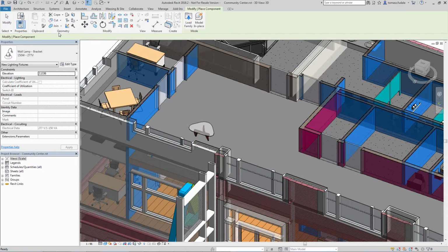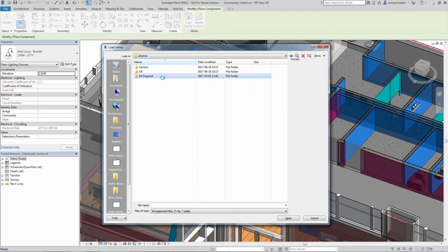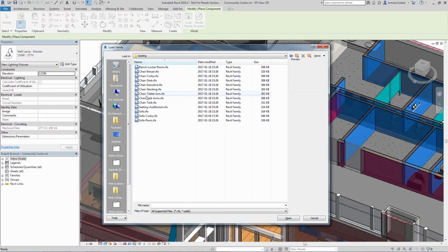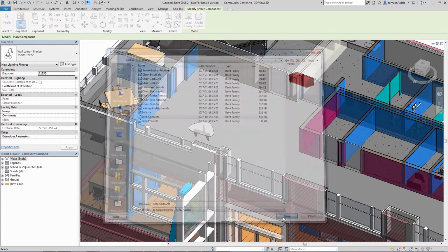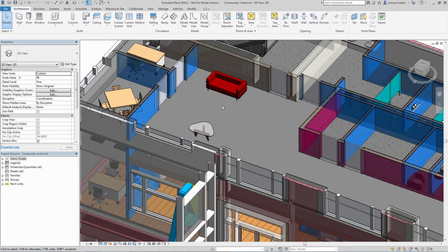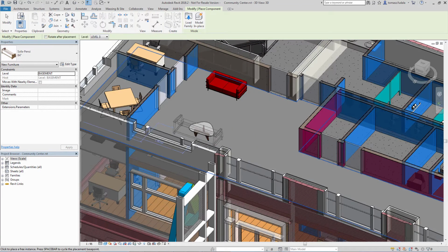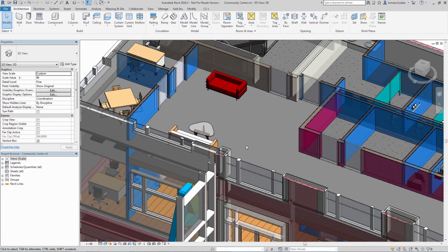In Revit 2018.2, once you load a family into the Revit session, the next time you load a family during that session, it remembers the location of the family you loaded last. You don't have to start from the default location and re-navigate to where the families are located. This improves your efficiency when working with Revit families, and you no longer need to rebrowse to the same network location over and over again in the same Revit session.